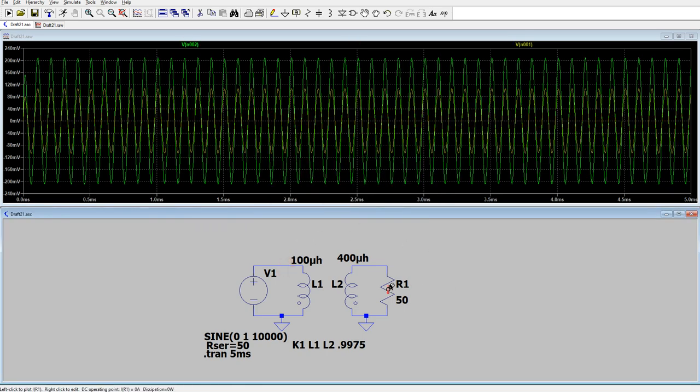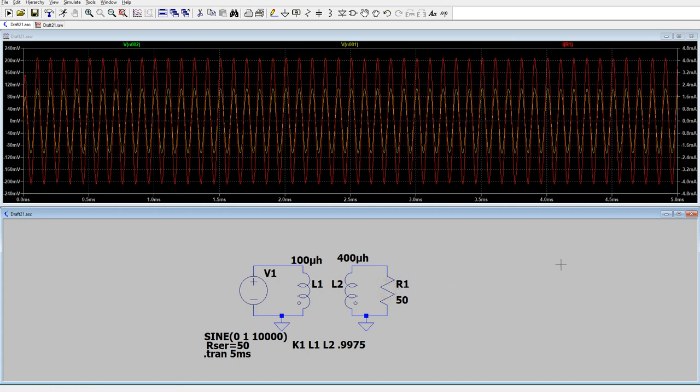If you want to see this current, boom, we add the current, and it's plotted over here, and it's the red one. So it's sitting in the little over 4 milliamps. Get the peak current here. It's 4.1 milliamps peak. Maybe there's some inductive peaking going on there or something. Anyway, it seems like it should be 4, just based on round numbers. But we can remove the current.